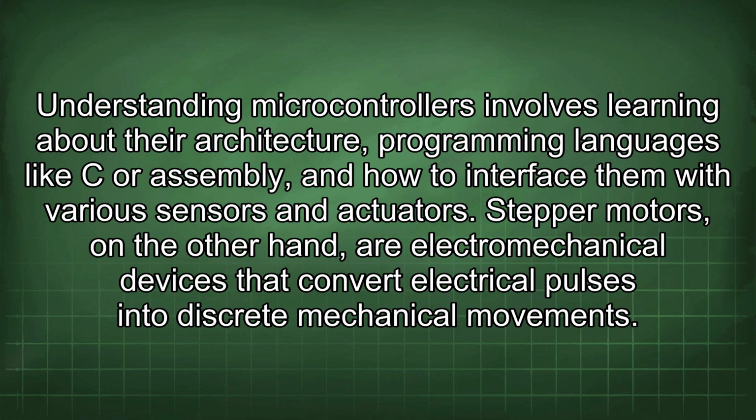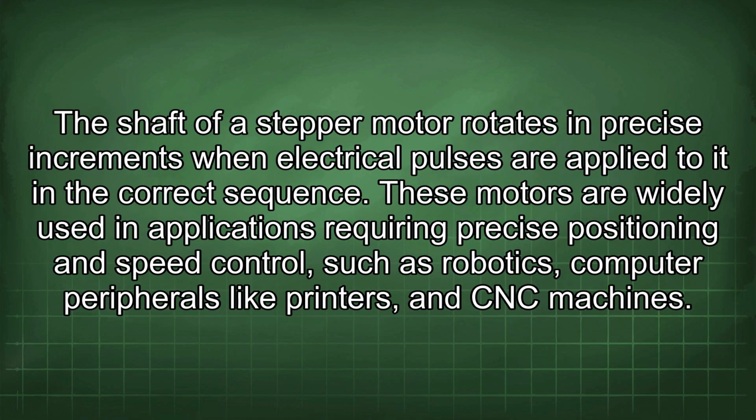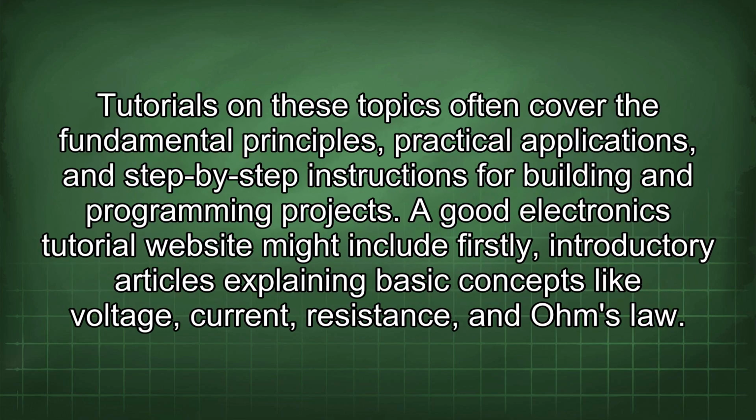sensors and actuators. Stepper motors, on the other hand, are electromechanical devices that convert electrical pulses into discrete mechanical movements. The shaft of a stepper motor rotates in precise increments when electrical pulses are applied to it in the correct sequence. These motors are widely used in applications requiring precise positioning and speed control, such as robotics, computer peripherals like printers, and CNC machines. Tutorials on these topics often cover the fundamental principles, practical applications, and step-by-step instructions for building